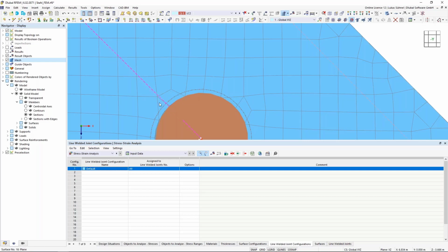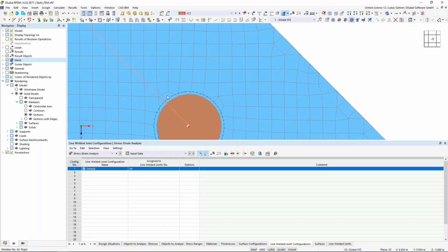If we reduce the stiffness, it means they will deform much more than the other elements, which, with the regular stiffness, will take or overtake more of those forces until they maybe also reach the limit stress. Then we will reduce the stiffness again, and so on and so forth. That's the logic that we're using here. So we take a look at each FE element, and since we do it on this FE element basis, we should also check the results on FE elements.